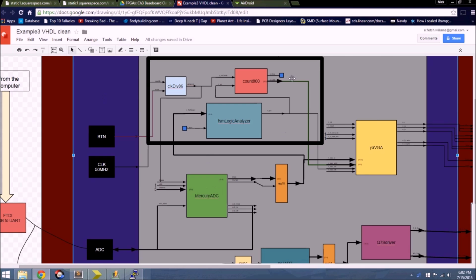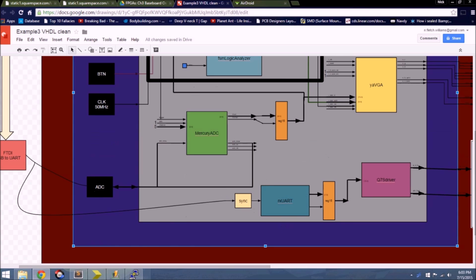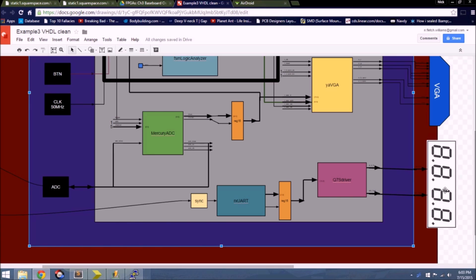You could see that even though it looks pretty complicated, in reality it was pretty simple. So now I'm just going to go over these last 4 components, which take the digital UART signal waveform input and interpret it and display the value onto the 7-segment display. And as you saw in the demonstration earlier, it will display the most recent value received on the less significant byte end here, and then the previous UART signal will be stored here.